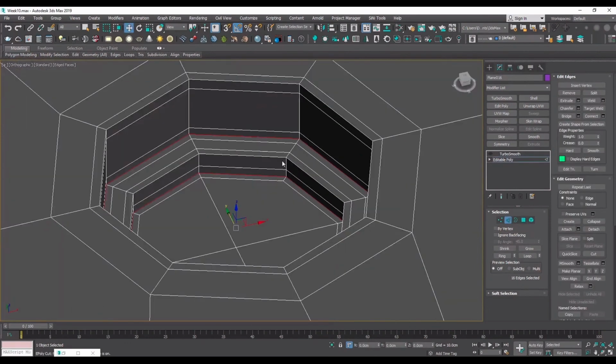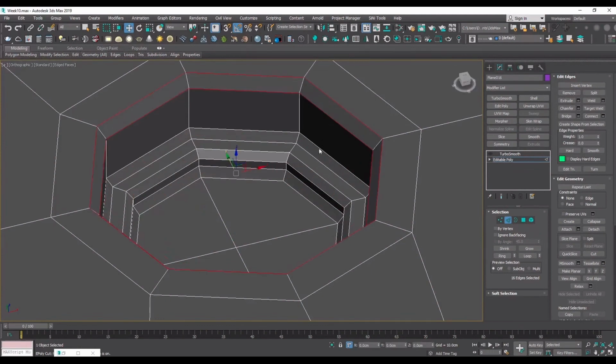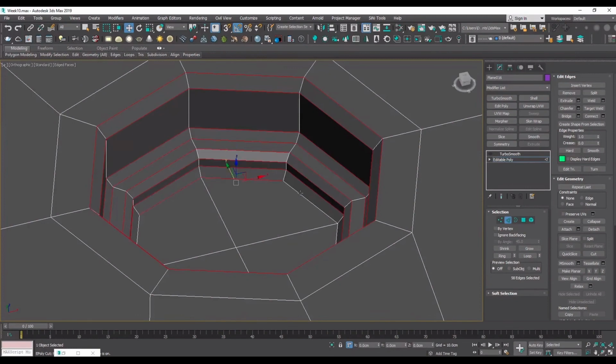What I'm going to do is basically go for the chamfer effect that we had earlier. And also I'm going to create another edge and then select the middle edges and just control remove them to get this type of geometry. And then I'm going to again select the edges and repeat our chamfer operation to preserve our chamfer effect, as we have done in the past numerous times now.